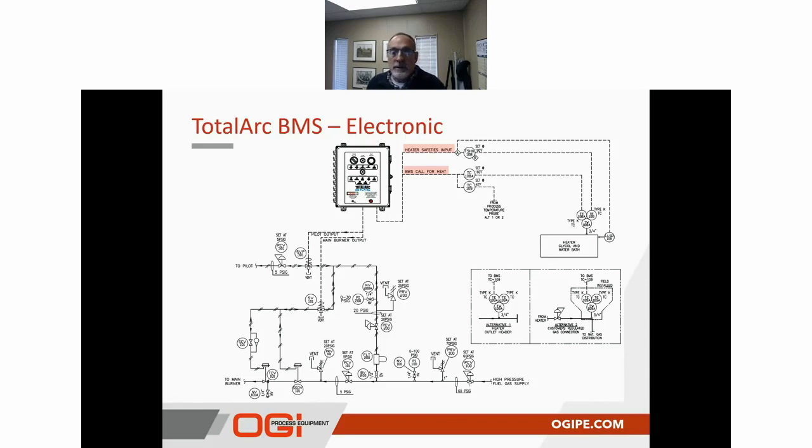Some just want a process temperature control. In the process temperature control, we've seen typically there's two alternatives. As you can see here, we have either alternative one where the temperature control monitoring point is located in the outlet of the heater, or alternative two where it's located downstream of a client's regulator.